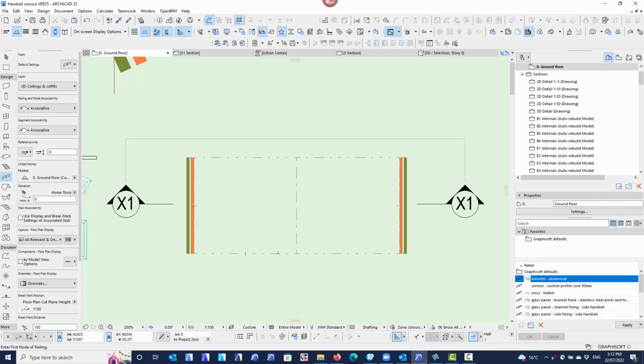The trick is that when you use the magic wand, go close to the node that you want to start and stop at. So it could be that one, it could be this one. I'm going to start and stop deliberately at the apex of the roof, at the ridge. The reason being is the railing, when it goes around the room, has to have a start and a stop point. If I start and stop in a corner, they will not mitre, because it's a right angle end, if you like. You can't mitre the ends of a railing. So don't start in a corner, start at a gable or the ridge. If you can't do that, start halfway along one of the walls. It's just that wherever you start and stop, you're actually going to see a join line.